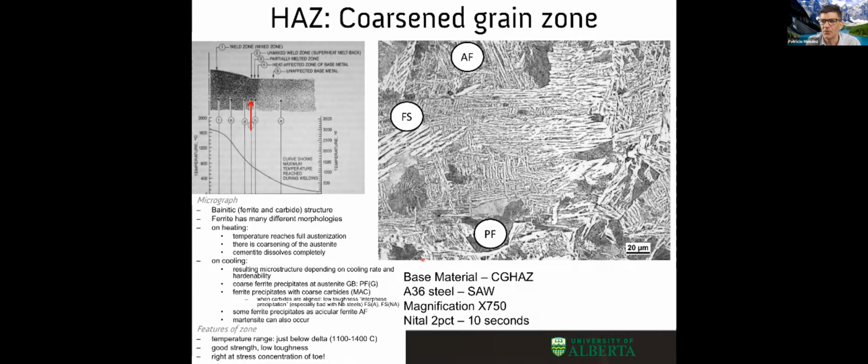So if you remember, something actually is for today's quiz: big austenite grains are very hardenable. Big austenite grains are the equivalent of having a very fast cooling rate. Or big austenite grains are the equivalent of having a high alloy content. The alloy is the same. It's just the big austenite grain, and the cooling rate is the same. What changed here is the prior austenite grain size.